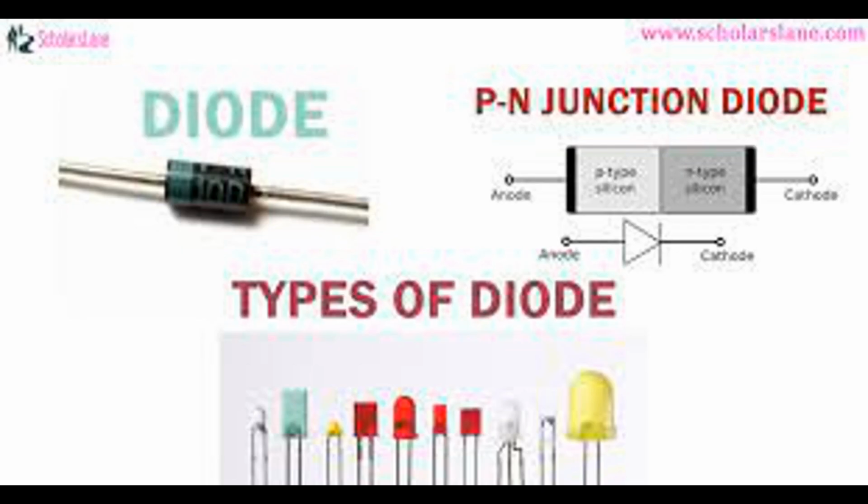Circuit configuration. In a diode clipping circuit, one or more diodes are placed in series with the input signal. The diode conducts and allows the signal to pass through only when the signal voltage is within a certain range, determined by the diode's forward voltage drop.